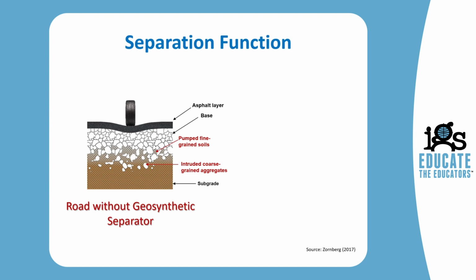One of them is when the gravel material has a localized bearing capacity failure and is punched into the underlying subgrade. An additional mechanism has to do with the presence of water. Because of the dynamic loading of the traffic, the pulses will create a pumping and the fines will go upward and contaminate the base material. So we have downward mechanisms of failure and upward contamination as well.